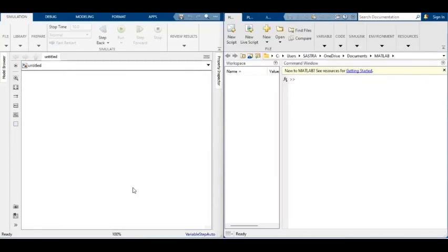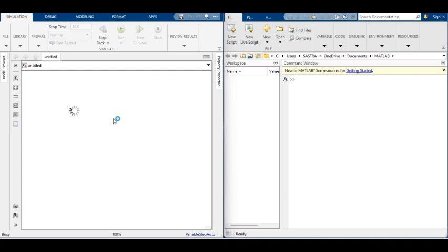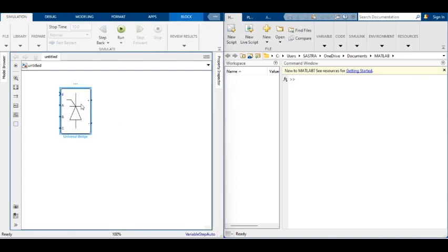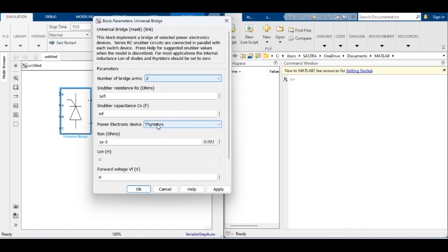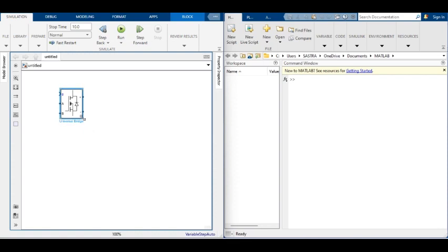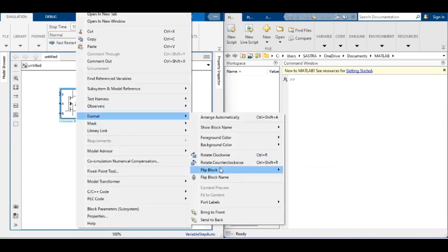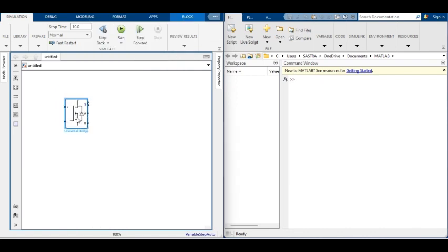Hi. In this video, the three-phase 9-level inverter-fed induction motor drive is simulated using MATLAB. First, the single-phase 9-level inverter topology is built with SimScape and specialized power system components. Two universal H-bridge modules are taken and configured as single-phase MOSFET H-bridge inverter. Both are connected and gating pulses are combined through the multiplexer to construct a single-phase 9-level cascaded H-bridge multi-level inverter.